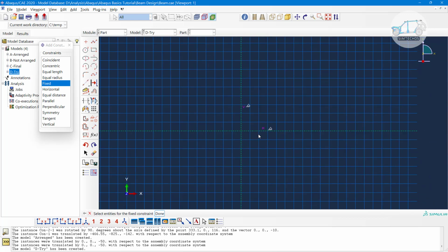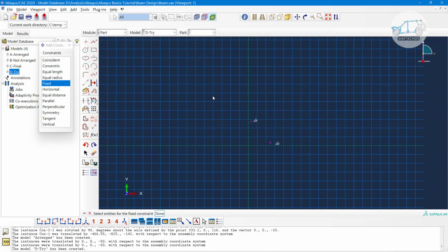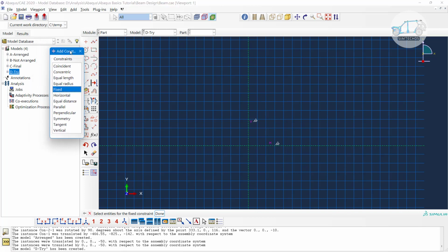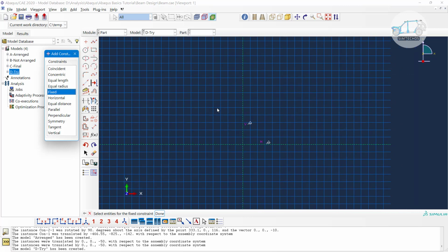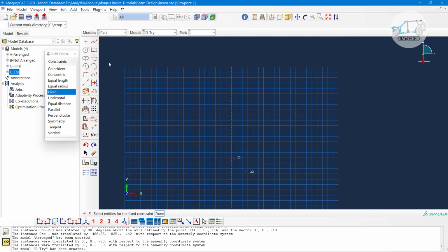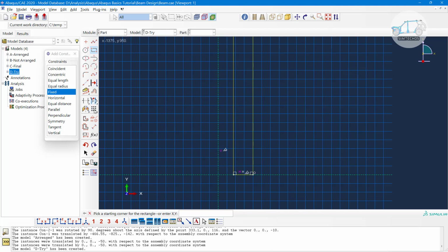Okay, here we are performing part modeling, but within the part itself we are going to make a number of components. So this geometrical constraint toolbar is very important, so I'm not going to close it. Now I have to create the concrete columns, and we need to provide the dimensions.